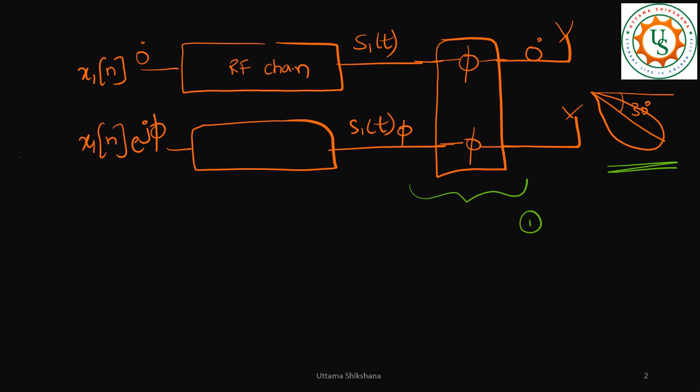Then in the previous video, especially with respect to hybrid beamforming, I was mentioning that instead of using these phase shifters, we can perform a similar phase shift operation in the digital domain, something like this, so that we will have the equivalent effect of phase shift across the chain, and hence the RF beam can be formed in the required direction, right? So now we will see, with these two concepts, how precoding-based beamforming is influencing the RF beam.